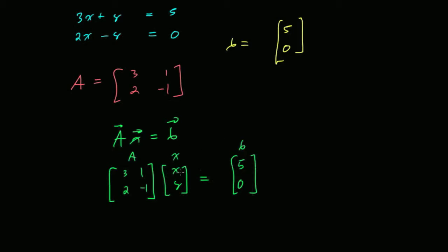You can do it in Matlab. You could probably do it in just about any other number crunching tool out there, right? It's just a standard trick. The actual software you use to solve it is besides the point. It's a standard matrix solving tool. In Matlab, the specific command that I'm going to show you is you say A / B, and that will actually give you the coefficients.